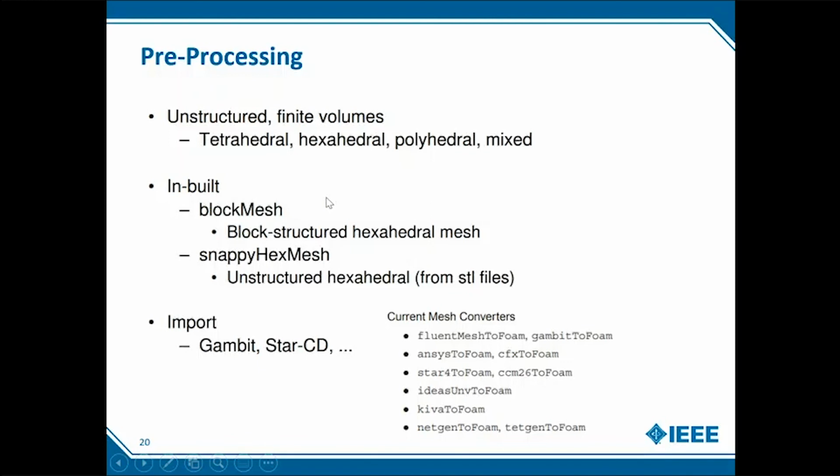Otherwise it will shoot out an error saying blockmesh with a small m, command not found, something like that. So basically this is the command you type in your terminal, blockMesh, and your mesh will basically come in your domain. And snappyHexMesh is more of a complex command.